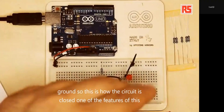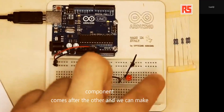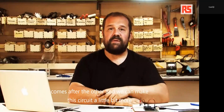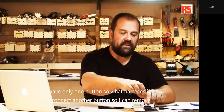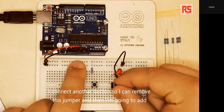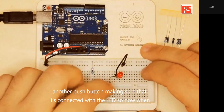One of the features of this circuit is that the elements are connected in series, because one component comes after the other. And we can make this circuit a little bit more complicated because at the moment we have only one button. So what happens if I connect another button? I can remove this jumper, and then I'm going to add another push button, making sure that it's connected with the LED.